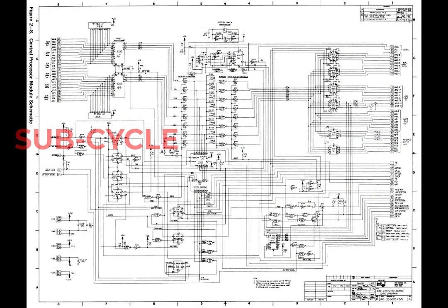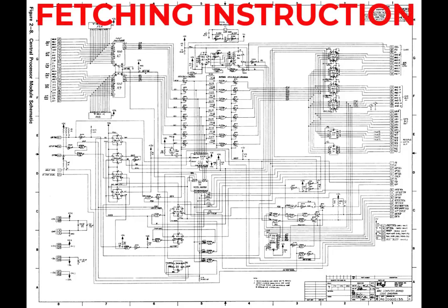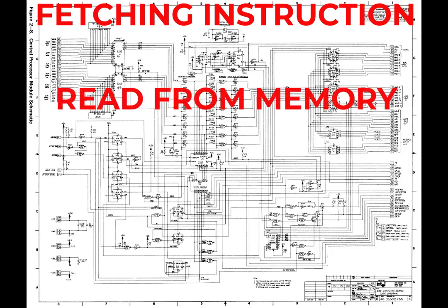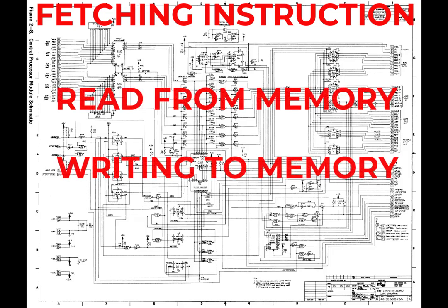As you can imagine, it's critical for the entire system to know what the processor is doing as it's fetching these instructions and exchanging data with memory, or when it's reading or writing to an I/O port for that matter. There's 4 top-level categories the processor can be doing. It can be fetching an instruction, reading from memory, writing to memory, or doing I/O with a port. And each of these subcycles has a name, and all the documentation for the 8008 refers to these names, so it's important to understand and keep them apart. And fortunately, these names are easy.